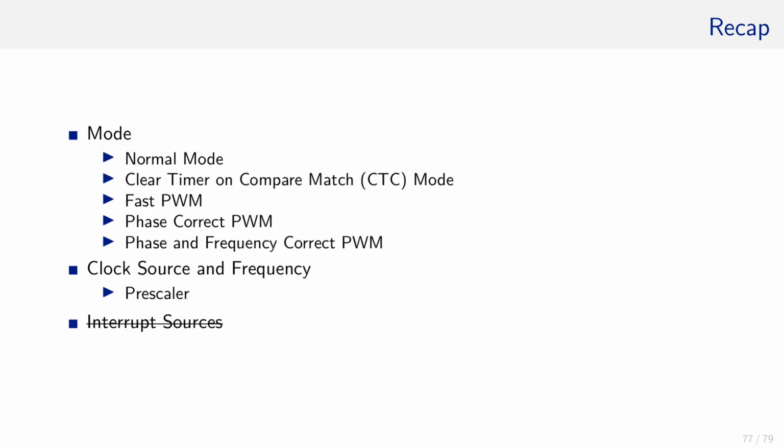For instance, if the input capture unit copied the value from TCNT to ICR, how will the software ever get to know that such an event occurred? The events might occur in irregular intervals, and checking ICR for a change will consume CPU computation resources. Or another scenario, you use timer 2 as a real-time clock to measure when 1 second has passed. How will you get to know that the timer overflowed?